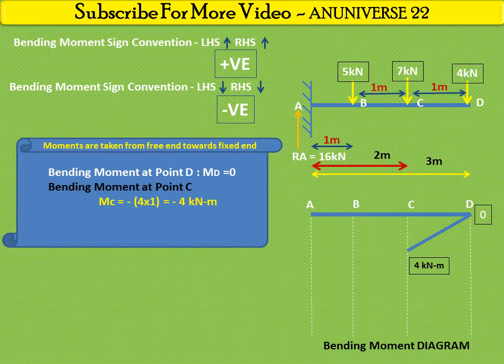Now the bending moment at point B. The distance between B and C is 1 meter, and the distance between B and D is 2 meters. For calculating the bending moment at point B, the 4 kilonewton load and the 7 kilonewton load both move toward B. The 4 kilonewton load covers a distance of 2 meters, so that is 4 into 2, negative because it is downward.